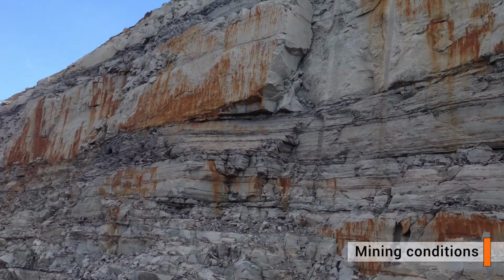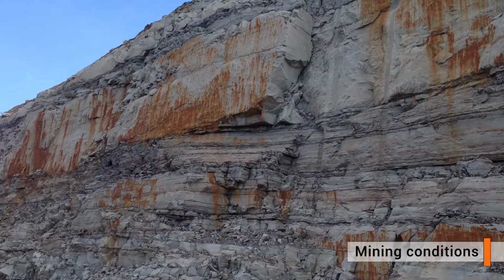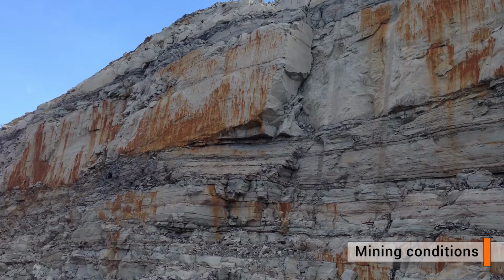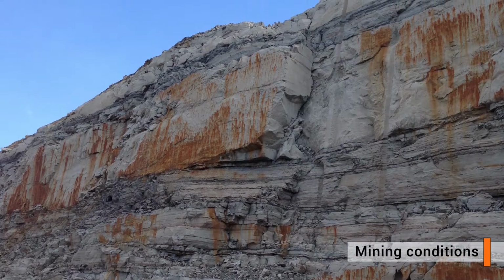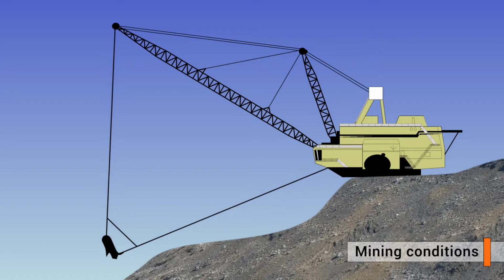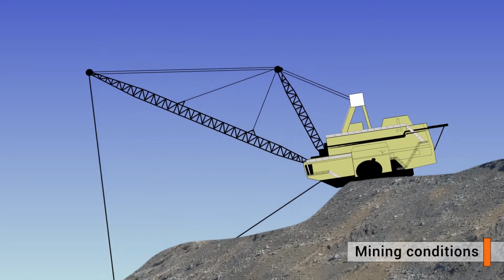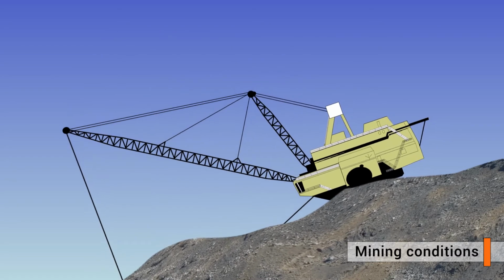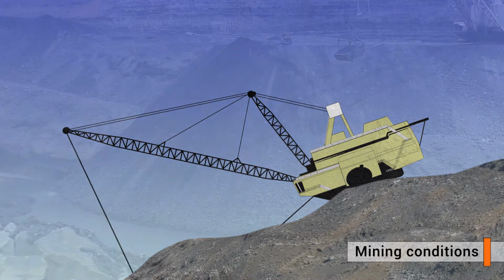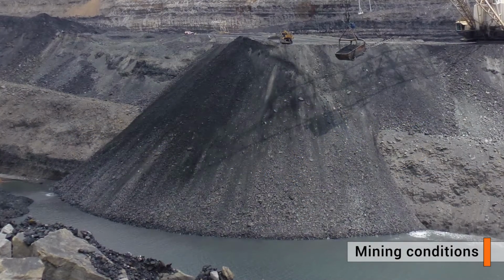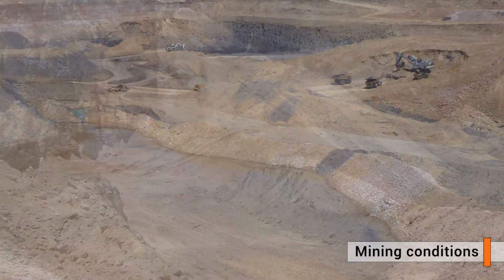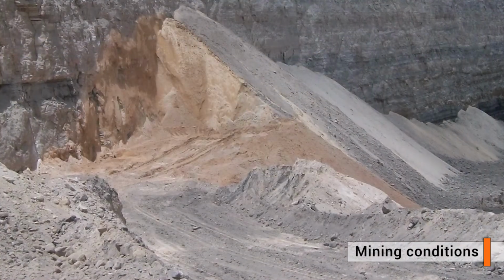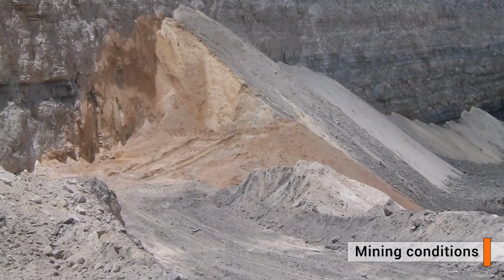Poor blasting and excavation practices that leave hang-up or jagged excavated faces, particularly around transition zones from soft walls to high walls. Loading conditions, such as waste material or equipment being positioned too close to the dump or high wall crest. Dumping of waste material into water or mud, leading to degradation of waste material strength. Dumping sandy or highly weathered material at the base of a dump.